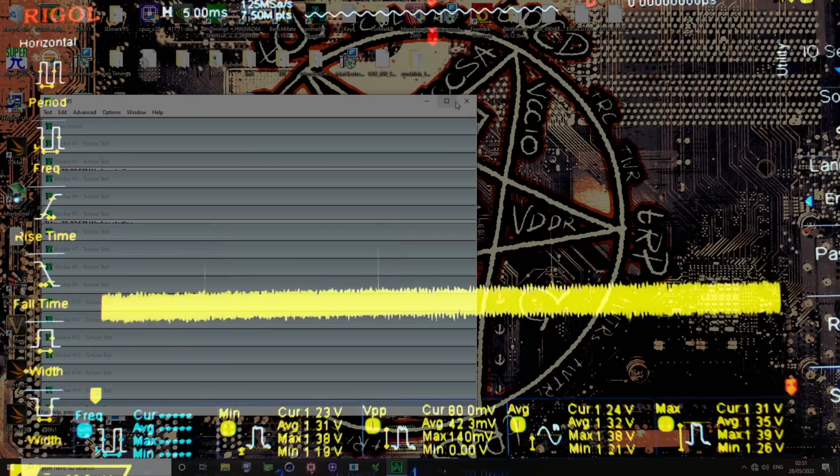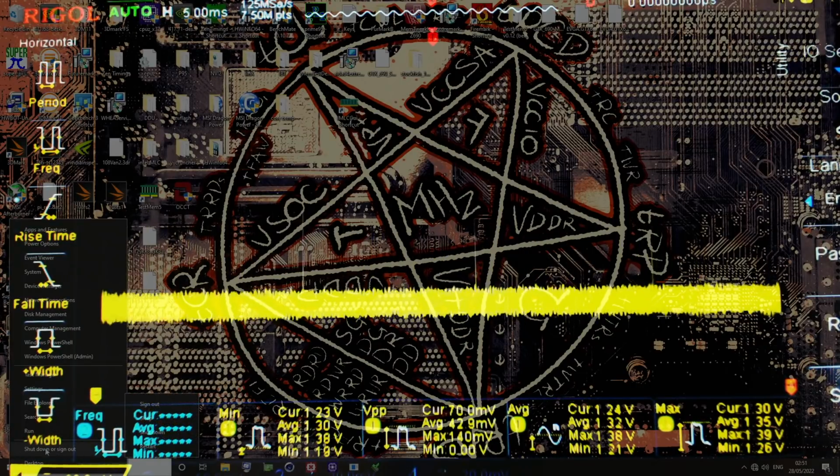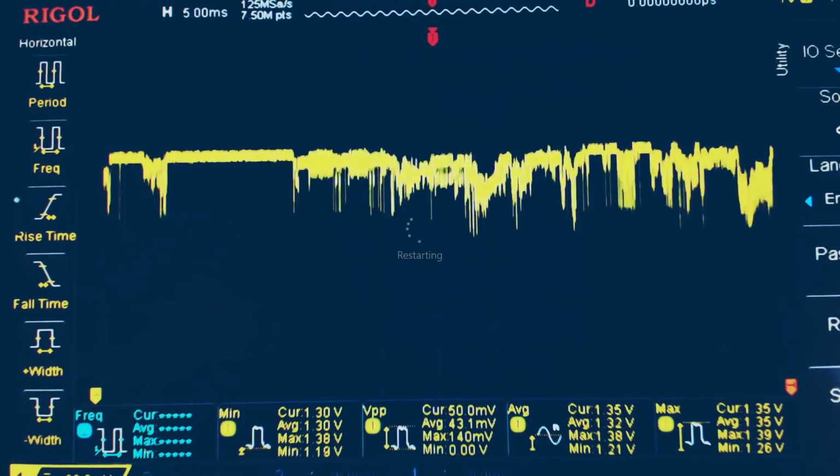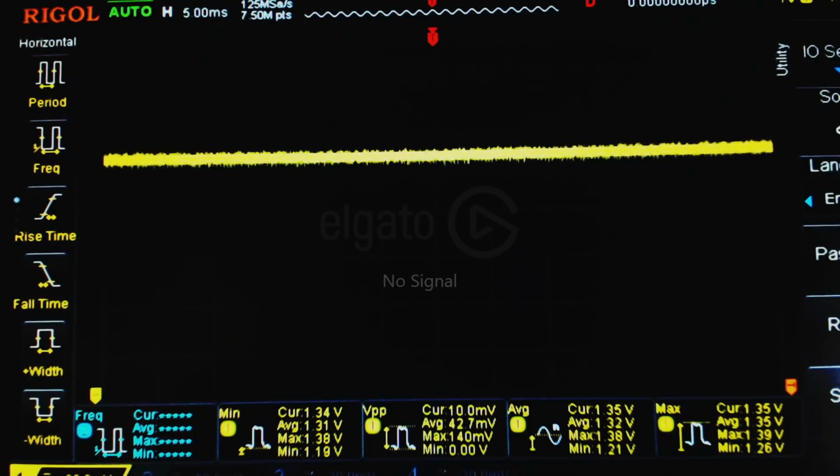The whole reason the Super I/O is so bad at measuring core voltage on a normal motherboard is because the Super I/O lives in the middle of nowhere relative to the CPU. And you don't want to be running your extremely sensitive die sense lines to the middle of nowhere.